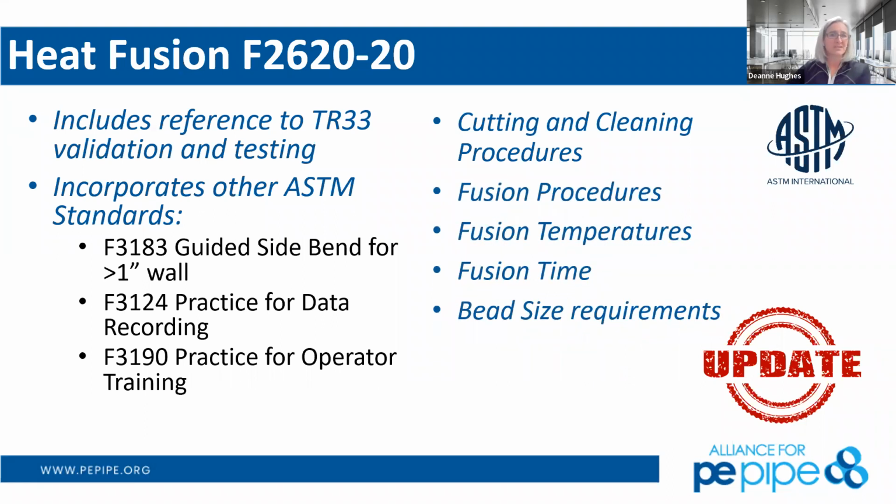From a standpoint of the procedures and the temperatures and the time and the bead size, those things have all been very consistent since about 2012. And it still does indicate that fusion joining is not recommended in ambient temperatures below -4. I don't want to be out if it's -4, and I'm sure that you don't either. So no, I don't think that's too bad of an idea.